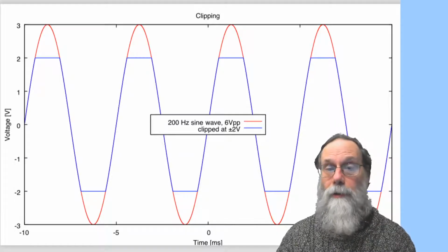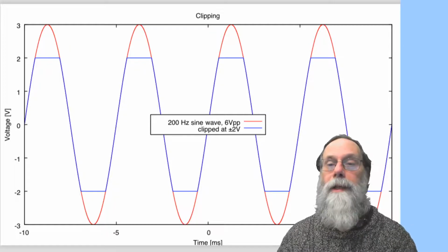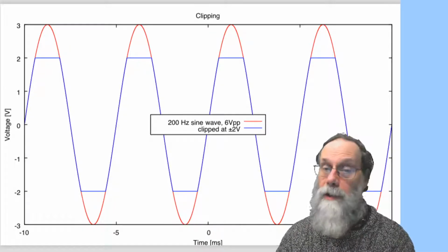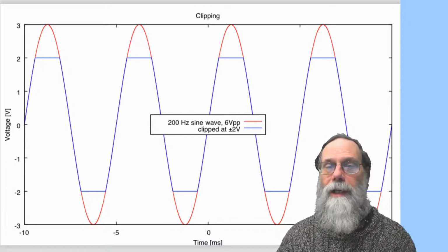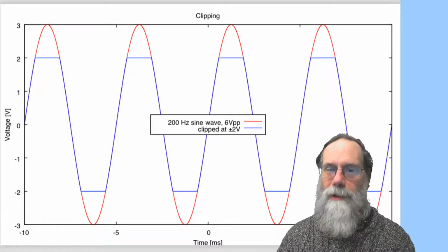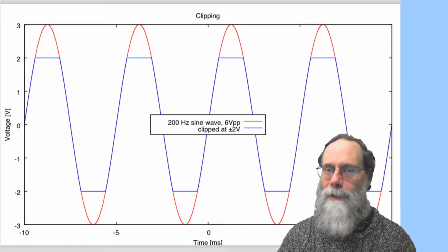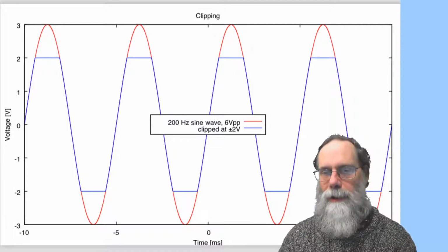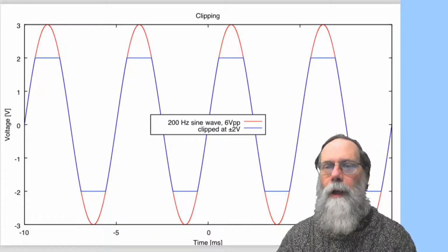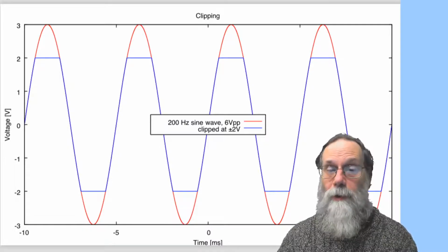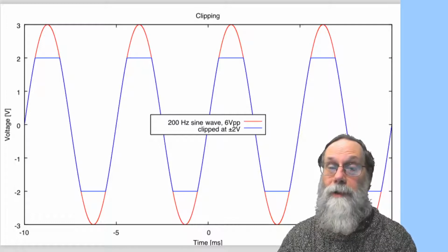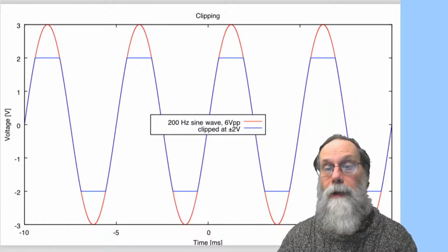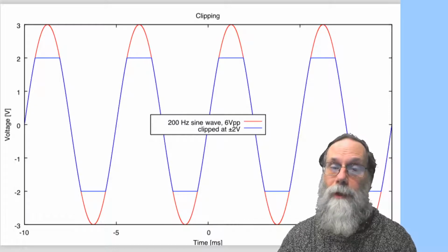Now, there are amplifiers that are designed to do distortion. Some guitar amplifiers, the old tube amplifiers and ones that try to imitate them, deliberately distort the waveform in a way that's different from clipping. They produce a softer transform function, one that doesn't have a sharp corner going from linear to constant, but has a sort of rounded, slowly reaching a limit. And that sort of distortion changes the sound quite a bit, and people who play electric guitars often like the effect of the distortion that they get from those old amplifiers.